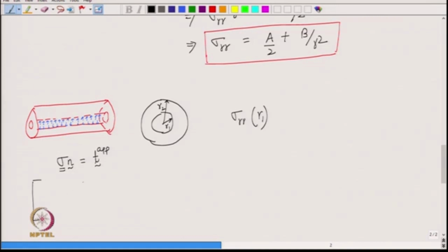When we write this in the E r E theta E z coordinate system, we have this stress matrix multiplied with minus 1 0 0, and this is equal to the traction being applied, and what we are applying is pressure in the positive E r direction. So, that traction will become P 0 0.